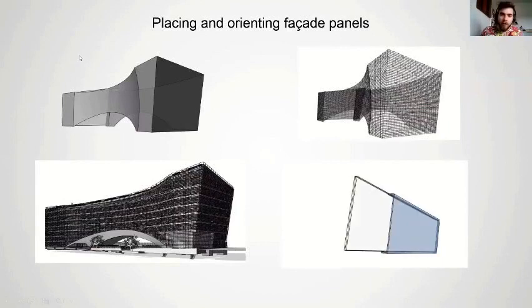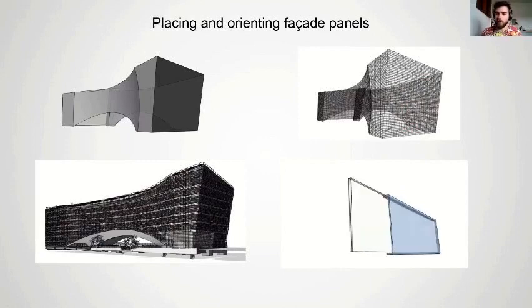Then with the help of Grasshopper, which was the other tool that I briefly mentioned at the beginning, that geometry was panelized. And the data for these panels was exported to Dynamo from Grasshopper in terms of vectors, points and vectors. So then these points and vectors were pushed into Dynamo, and Dynamo placed Revit generic components and adjusted their angles so they match the surface. And it had that information from these points and vectors from Rhino.